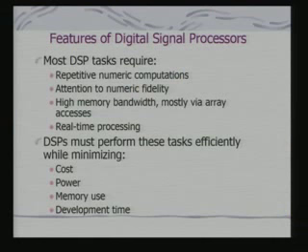And the other requirement is real time processing, and this real time requirement is imposed by the nature of the signal. As I was talking about, I have to obtain a pixel at a particular rate, satisfying the condition that I am taking frames at the rate of 25 hertz. And if I have to produce an output image at a particular rate, then my processing has to take place consistent with the sampling time period available with me. So, the external signal imposes real time constraints.